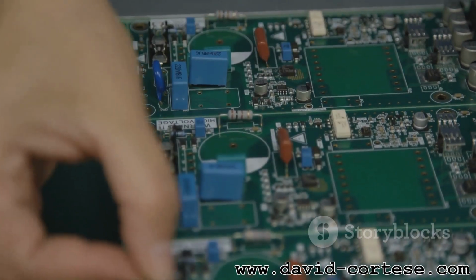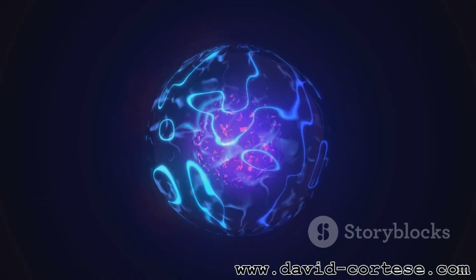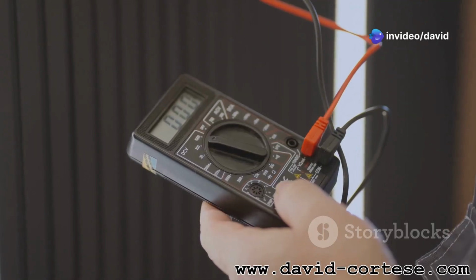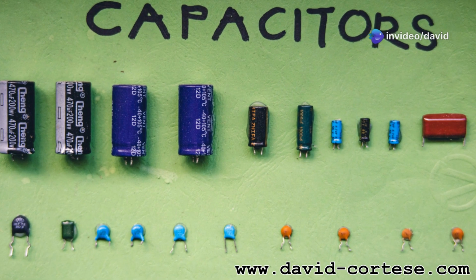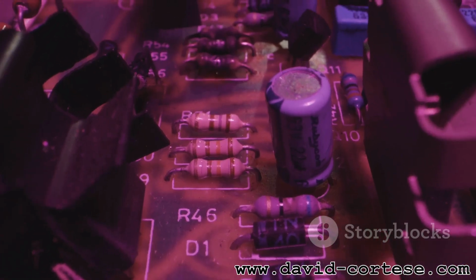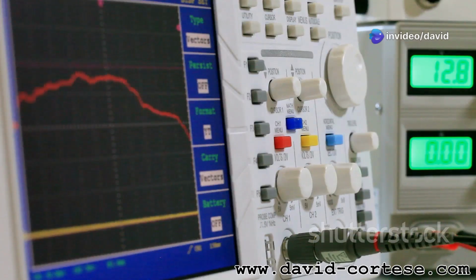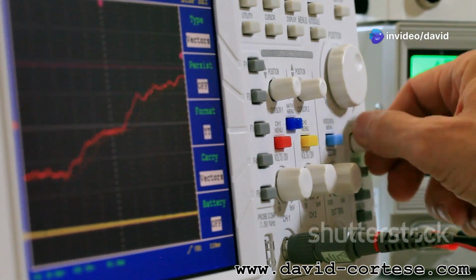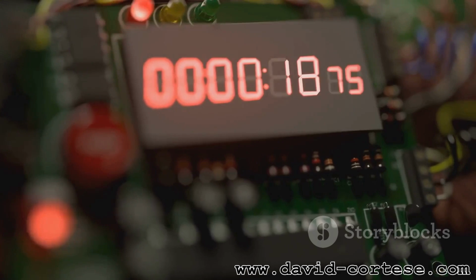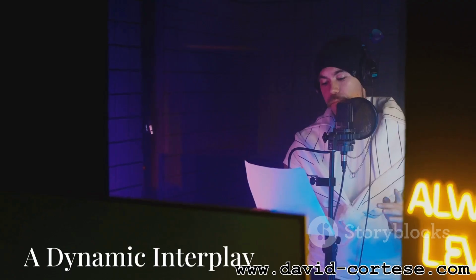When connected to a voltage source, it charges up, storing electrical energy. When the voltage is removed, the capacitor discharges, releasing the stored energy. The unit of capacitance is the farad. The larger the capacitance, the more electrical energy the capacitor can store. Capacitors are essential for filtering, smoothing, and timing applications in electronic circuits. In power supplies, capacitors help to smooth out voltage ripples, providing a stable DC output. In timing circuits, capacitors can be used to create time delays, like the pause between flashes in a camera flash.